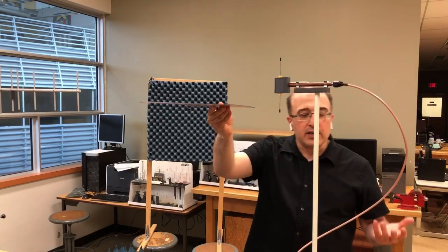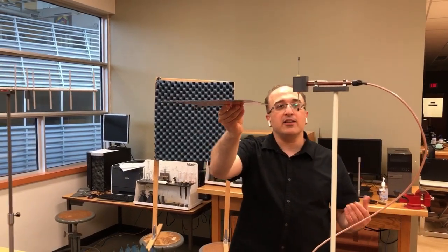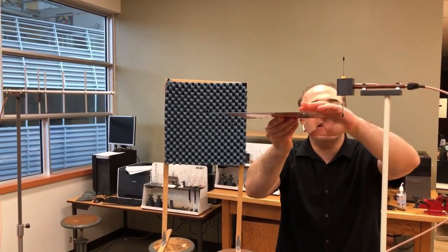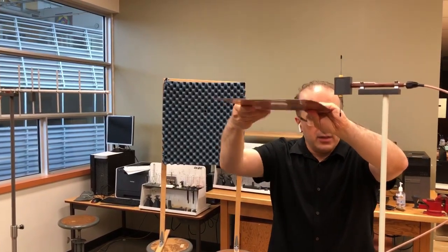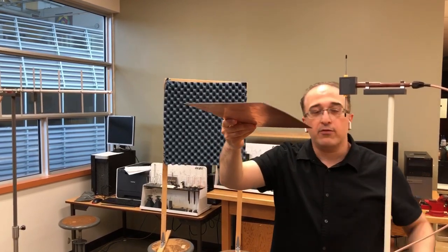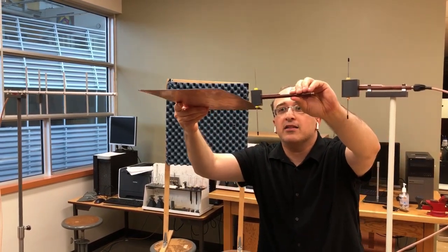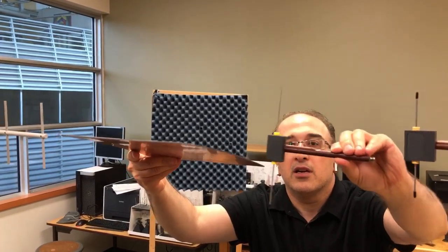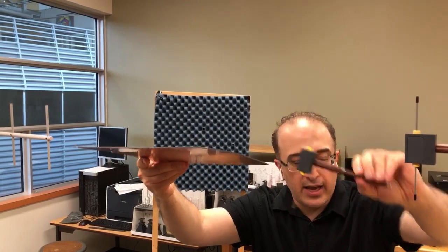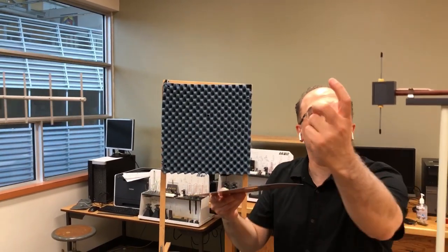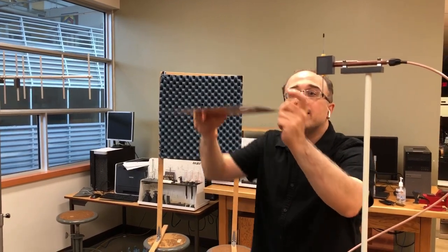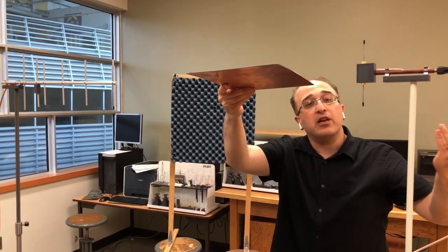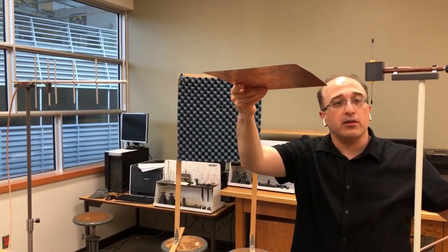Now, if you want to measure the radiation pattern in the H-plane cut, this antenna under test needs to move in the H-plane cut. So essentially, this antenna is going to be moving in the H-plane cut like that, which is completely okay using this system, because this system is going to rotate azimuthally. So you're moving in the H-plane cut and measuring the radiation pattern in this cut.